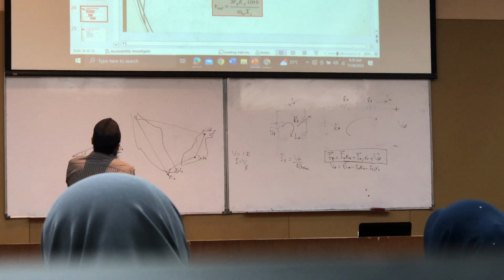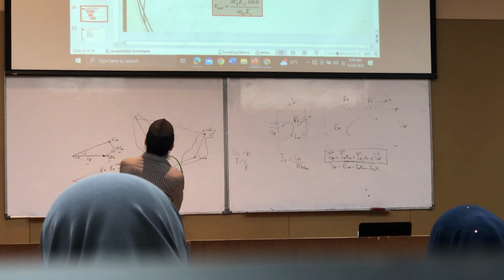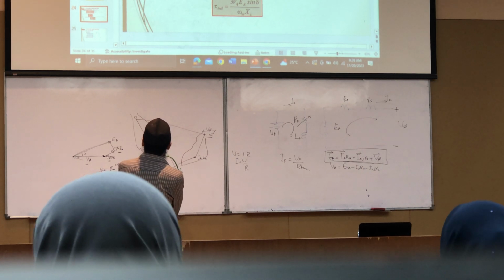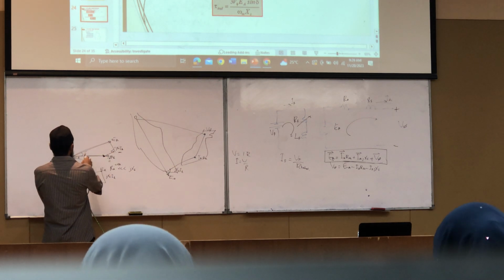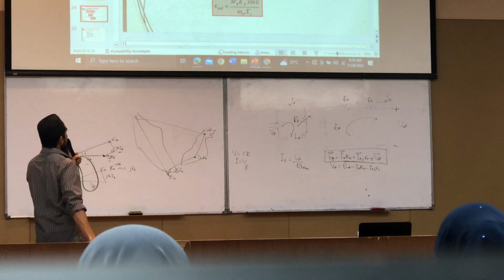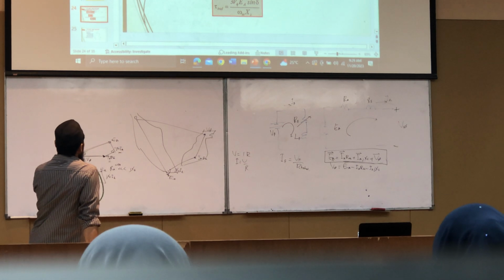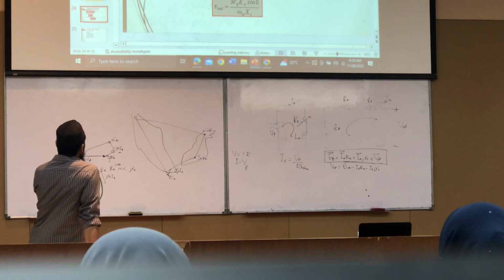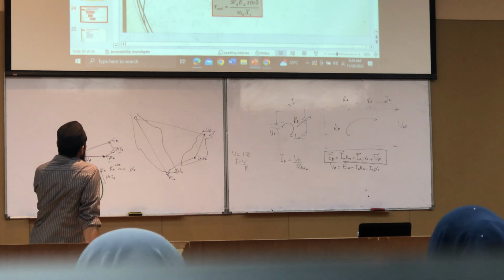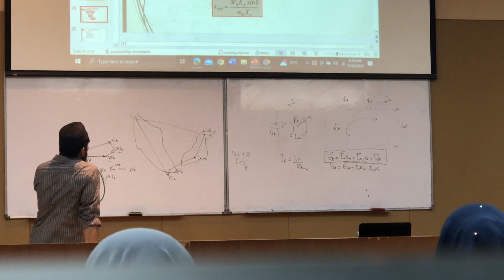Okay, for this diagram, we can see that the generated power will be maximum when our delta here at 90 degree. So P max will be 3 times V phase times EA divided by XS. So this is the theory lah. Nanti when we take a look at our calculation, we can see clearly what the justification or to justify the theory lah.